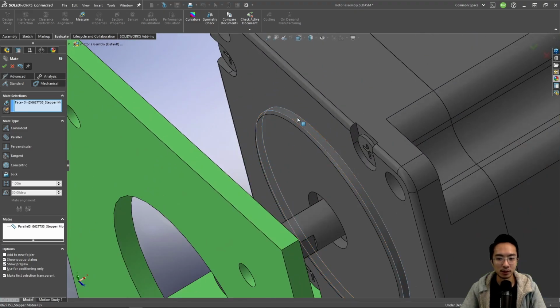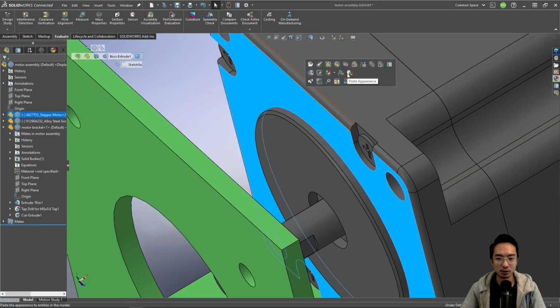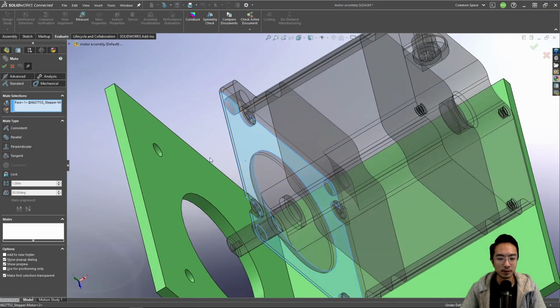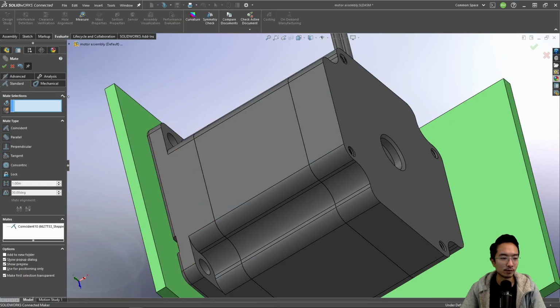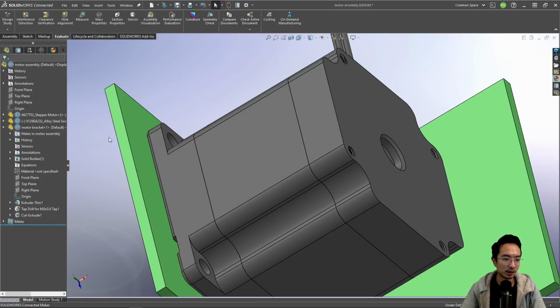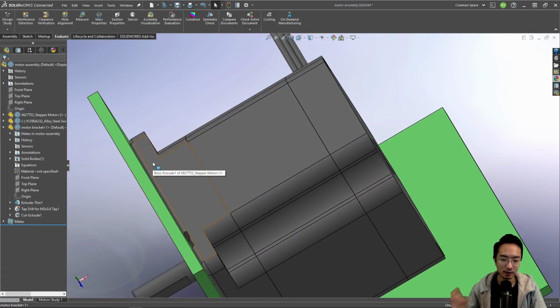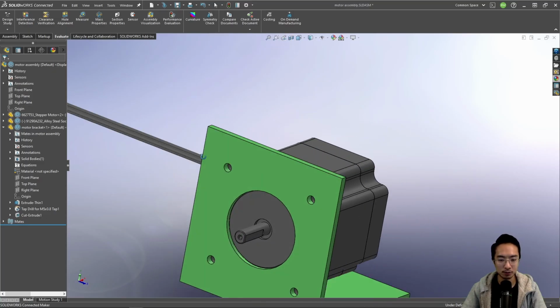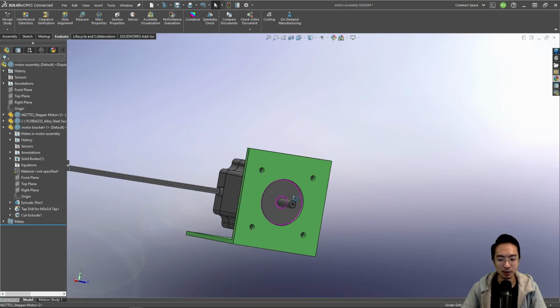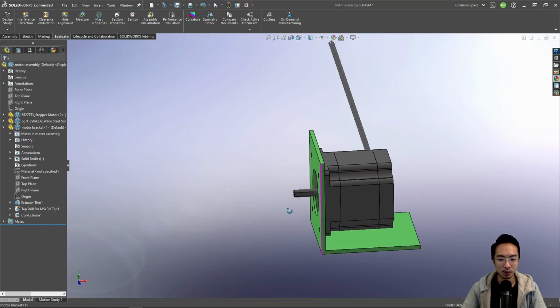And then from there, you could finally choose this face and then mate it to that face. And I did that pretty quickly, but what I did was once I clicked the 2 faces, I could right click and that will do like the check mark to allow the mate to finish. So that's how you mate the 2 parts here.